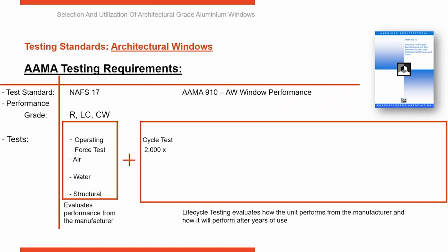So that's misuse testing. Or someone trying to force entry, break into a building. They're prying the vent away from the frame. That's misuse testing. So the product goes through abuse testing, then it's cycled 2,000 more times. Then we measure operating force and latching force.